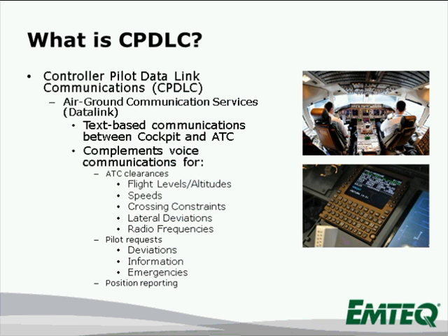with an overview of what CPDLC is. CPDLC is an acronym for Controller Pilot Datalink Communications, which is essentially an air-ground communication service using Datalink. In other words, it's text-based communications between the cockpit and air traffic control as opposed to voice communications, which are typical. This is meant to supplement the voice communications that have been existing for some time. Basically, anything that's provided currently via voice communications can be provided through text. So this would include any type of air traffic control clearances, any pilot requests, or any position report.